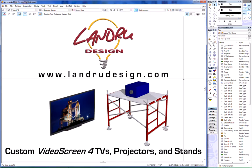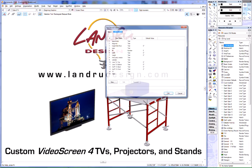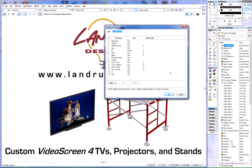Because they're symbols, we have to do something special with them in order for any of the VideoScreen tools to be able to use them. And that's this. We're going to apply this record that we see right here. I'm going to right-click on it and edit it so we can take a peek. There are 15 fields we see here. The last 2 are not used yet. That's for future expansion. These first 2, again, if you're running a more current version of Vectorworks, are not used at all. These are more for legacy use.